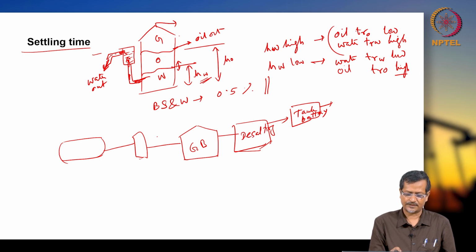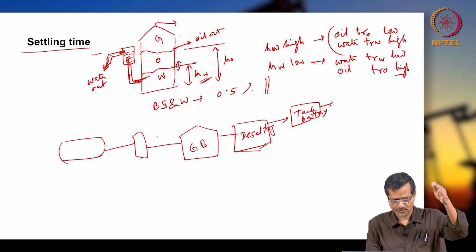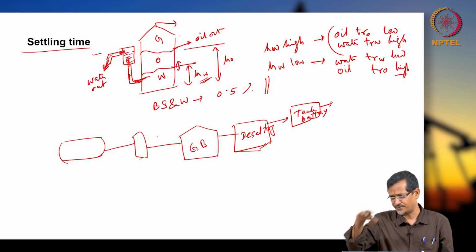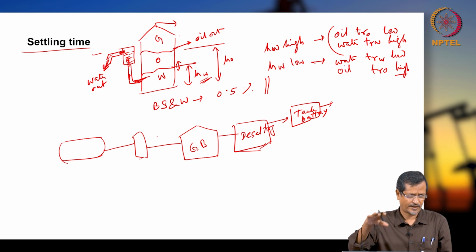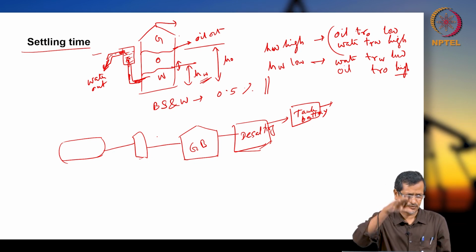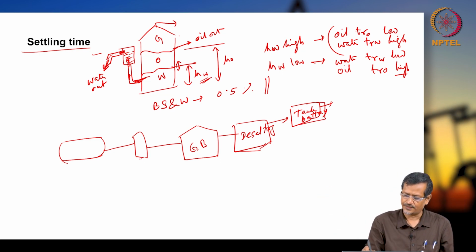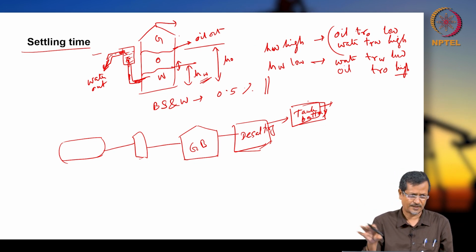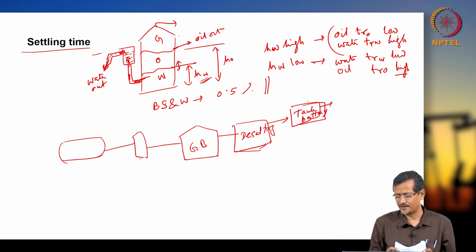Normally there will be a low pressure system and a high pressure system. Two-phase and three-phase separators are high pressure systems, though three-phase can also be lower pressure, but when you reach the gun barrel, pressure is very low. It is almost atmospheric pressure. Tank battery will also be at atmospheric pressure. Tank battery means several tanks storing oil before you send it to your customer or refineries. We will discuss later how the tank battery works, and the safety requirements, in later lectures on tank battery and storage systems.